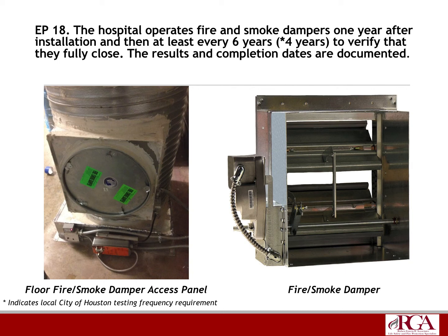They don't call them fire doors, they call them fire dampers. It's basically to provide that passive fire protection, that fire or smoke barrier. These have to be tested every 6 years for healthcare. Most of the time, you're going to be allowed to do it every 6 years. Now, here's the big catch: you have to do them 1 year after installation. So if you're a brand new facility, or if your facility is 1 or 2 years old, find out if you did the 1 year after installation.